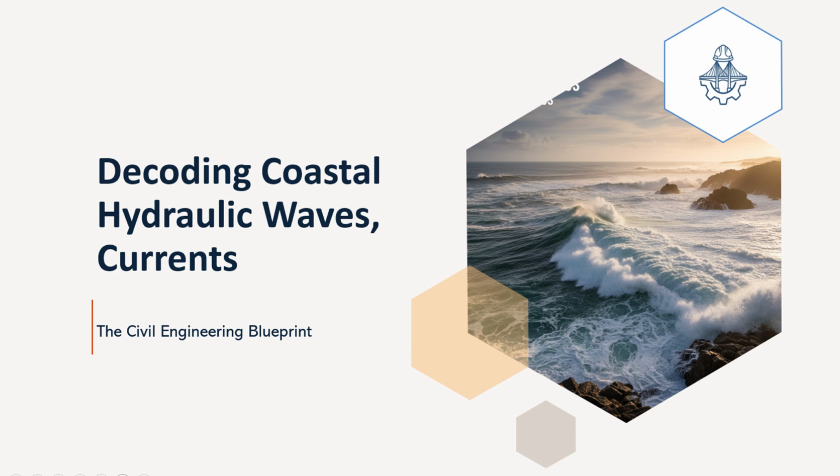This orbital motion is absolutely crucial for understanding how waves transfer energy, transport sediment, especially near the bed, and apply forces to submerged structures. It's far more complex than just pushing water forward in a straight line. And finally, for this foundational section on linear theory, let's uncover the pressure field. Under progressive waves, the hidden, fluctuating force beneath the surface that structures need to be designed to withstand.